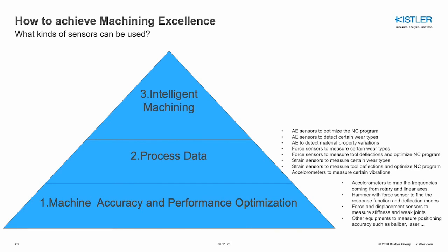And at the end, of course, in intelligent machining, what you do is that with those sensor inputs, you can build control loops, monitoring, or you can utilize those measurements in order to build a correlation between product quality parameters and those measurements. So you are utilizing that input for indirect measurement of certain quality parameters, so that you can decrease the amount of measurements, for instance.